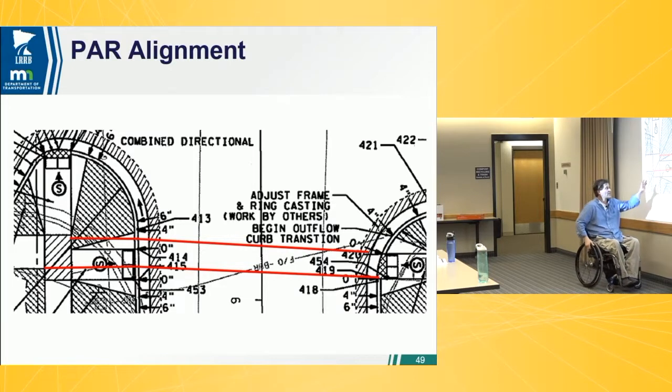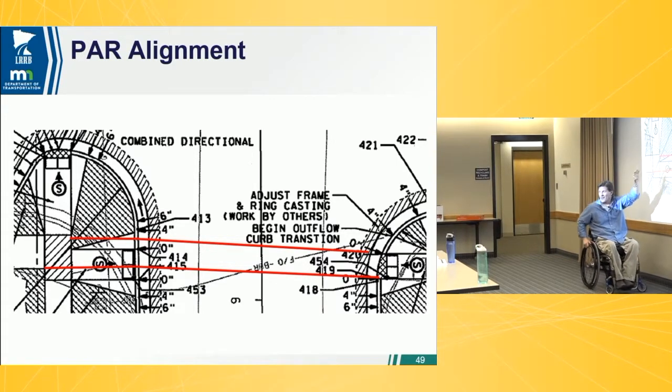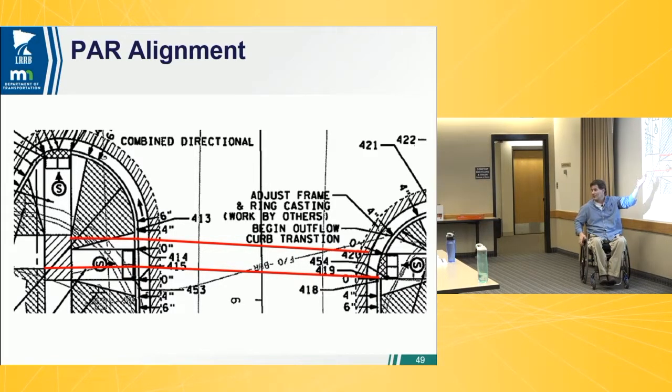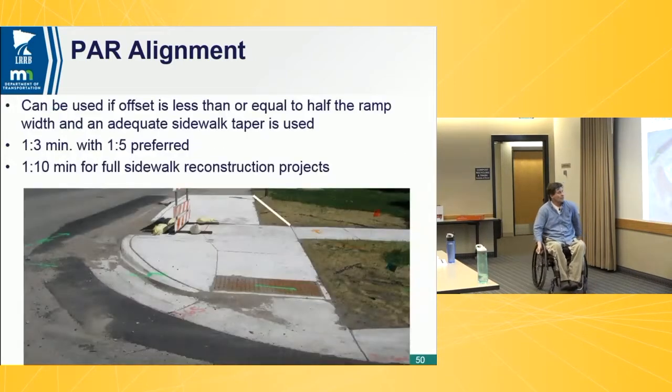But also, they don't understand when we make a recommendation, hey, why don't you just shift this curb ramp up 2 feet? Quite often, the designers are going to say, all right, who do you think you are? This is compliant. It's good enough. What makes your decision better than my decision or your opinion? And so again, we've got that luxury of hindsight and seeing the whole thing. You can see where even that 2-foot shift can make a big difference in how that sidewalk system gets used long term.